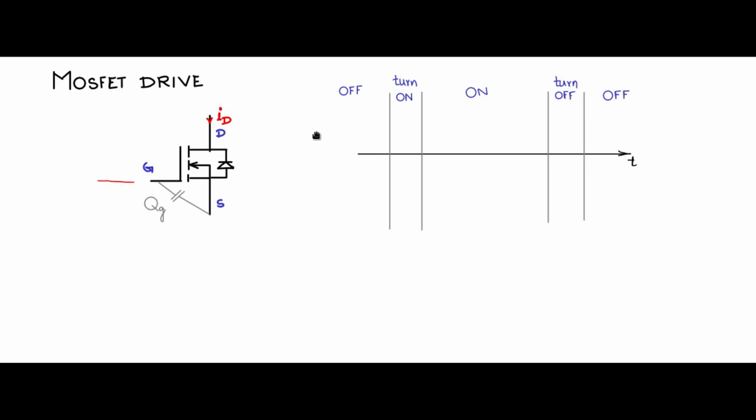So during this time, let us look at how the gate current IG looks like. So as I said, this is a charge control device, or a voltage control device. It is actually this charge that is important. So therefore, we will see how the gate current looks like based on that argument of giving a specific amount of charge to turn on the MOSFET.